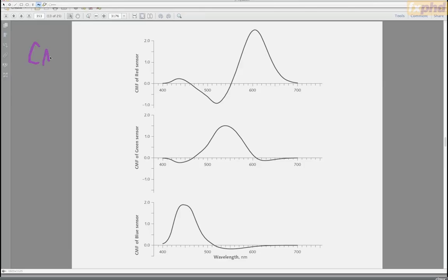These are called the color matching functions for 709 because I used 709 primaries in the display. And you can see that where in the previous case the X bar, Y bar, Z bar curves were all positive, these ones now have negative-going lobes. So you cannot build these curves directly, or at least you can't easily build these into the camera.